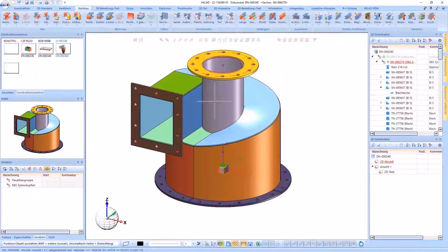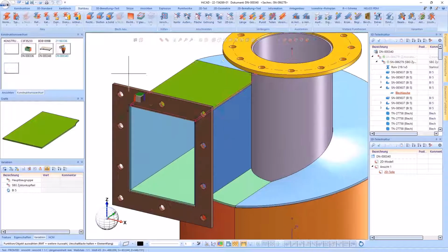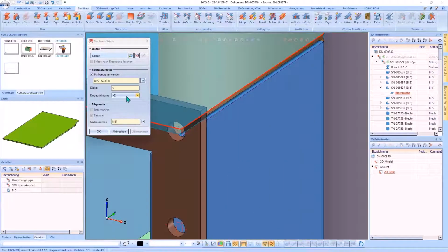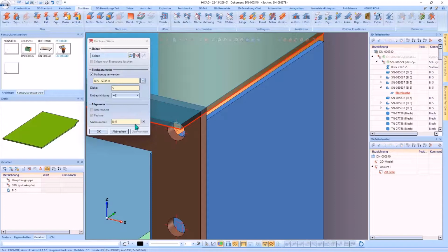Finally, I'll show you another nice innovation. You can double-click on a surface with the Elements snap. That means Shift to open the corresponding feature. This way you don't have to switch to the feature window to make changes afterwards.